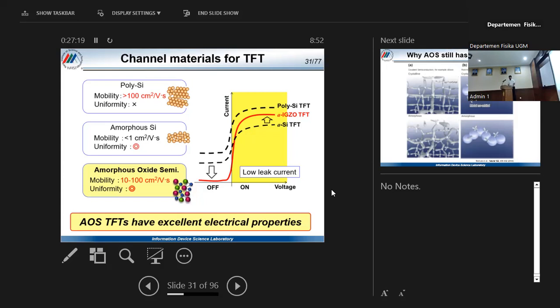This is because if you think about it, if your display is off or your device is off, it's actually not, so it's expending a lot of leakage current. If that leakage current is high, and if you have so many pixels, you're wasting a lot of energy or battery. So that's why old phones before have a very poor battery life. Now most devices use amorphous oxide semiconductors or the evolution of this amorphous oxide semiconductor.